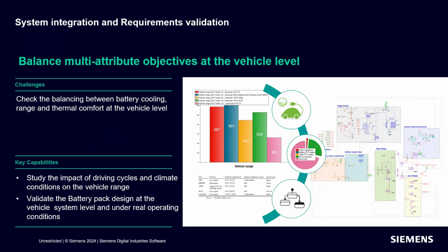And in this systems level model, like I just mentioned, we can include an embedded ROM, an embedded reduced order model type component, that we developed using SimCenter reduced order modeling to get the 3D fidelity in a much faster time. And this represents the full model for simulating the battery inside a vehicle along with the thermal management systems.